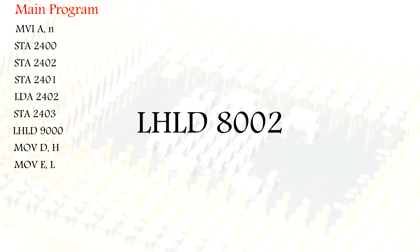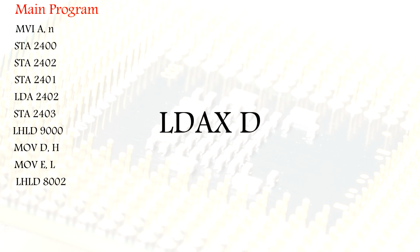Again we are calling LHLD 8002 and 8003, which carry 2501. So we are loading 2501 into the HL register pair. That is carrying the address of matrix A, where we have stored matrix A. At 4501 we have stored matrix B. So in DE we have 4501, in HL we have 2501.